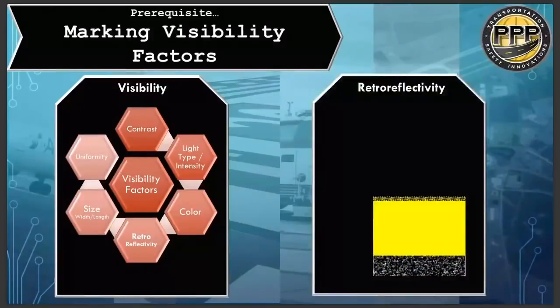You are looking at a graphic here. Essentially, you have a pavement. On the bottom portion, you have a binder or a coating like paint, like water-based paint, and then a glass bead that's embedded in that coating. And that embedment is very important for retroreflectivity and how it works, and whether it works properly or not.